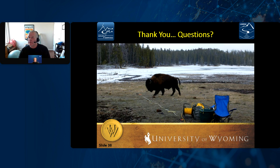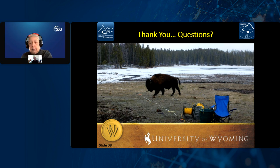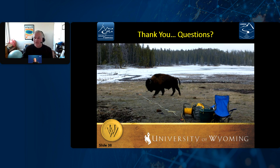Okay, thank you. We have lots of questions coming in. The first one, what is your gravity station spacing? Okay, nominally it was 50-meter across that site. There were a few areas that we got tacked on and asked to look at at the end, and so a few of them are 100-meter, but nominally it was 50-meter spacing. And then our gravity base was basically on a part of the site that was in the reduced area, so theoretically to the southeast in front of the roll front, which should have a minimal gravity signature.